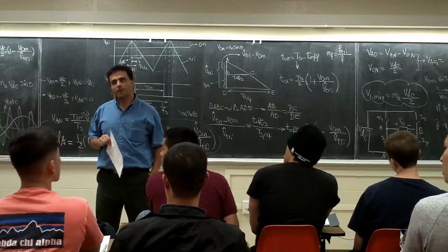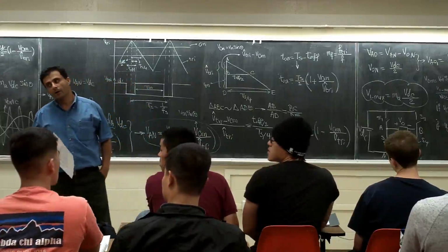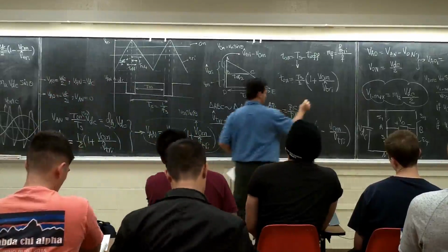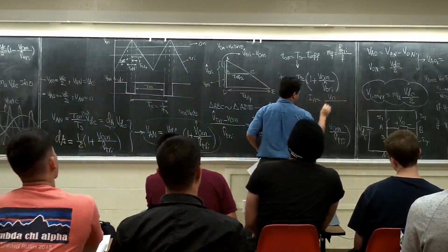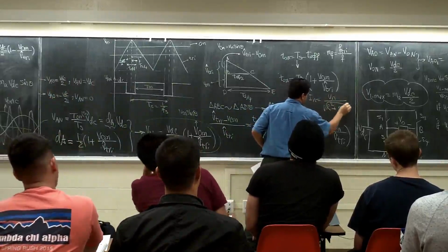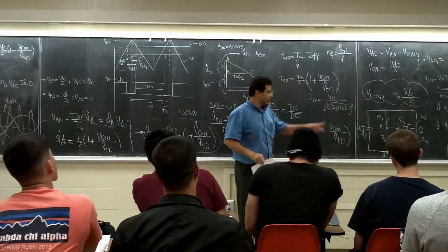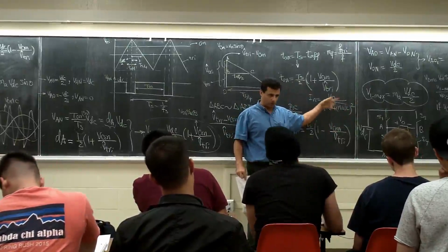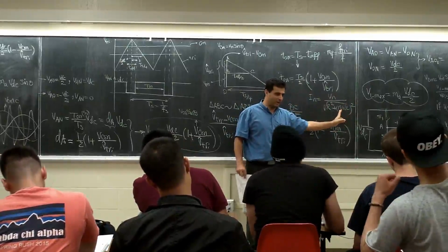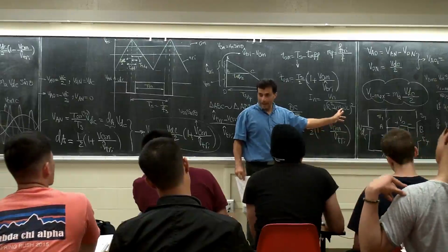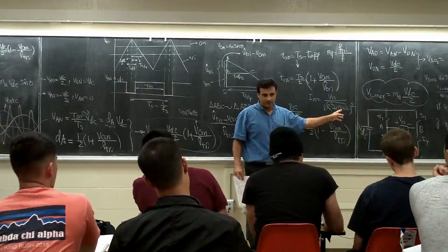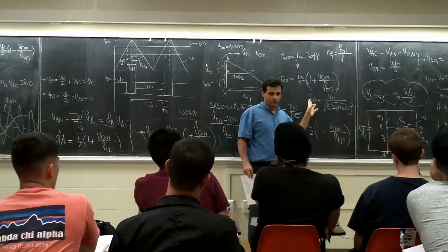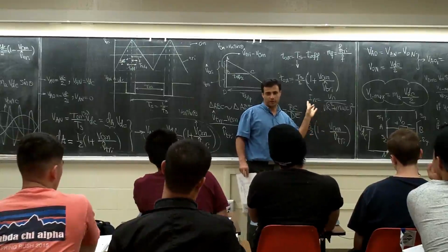100 actually lasts in the current. If you look at I_n, it's a V_n, right? If both of them, let's say 3 and 100, have 5 volt amplitude, this number is the same. But for 3, n is 3, and for 100, n is 100. Think about how much smaller I_100 is going to be compared to I_3. So what's the meaning of that? Better THD for the current, right?